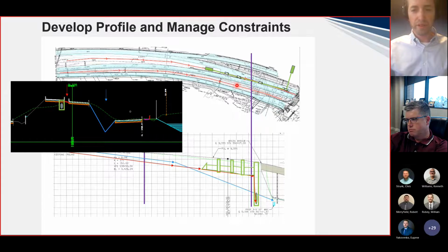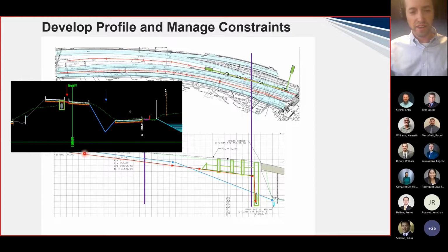So we have to check our ponding, and this is what we ended up doing, putting a series of inlets here. And now our outfall is actually over here, this ditch that we were draining to. So we know these frontage roads are low. So at the end, we need to drop the system and come out to that ditch. So our drainage profile, we've worked this whole side now, and it's come down here. We can keep it reasonably shallow through this area, so we're not having to construct a deep storm drain system. But then we're going to have to drop the system to get across the frontage road. So then we drop it and go out to the ditch. So this is our drainage profile for that side.